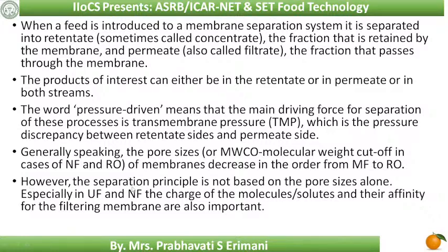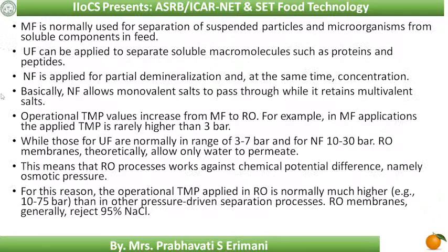The separation principle is not on pore size alone, especially in the case of ultrafiltration and nanofiltration. The charge of the molecules or solutes and their affinity for the filtering membrane is also important. Affinity towards the membrane as well as charge of the molecules, so both are important.